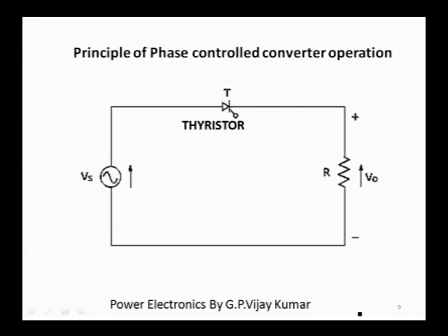You have already seen what commutation is. Commutation is the process of turning off a thyristor. So, this is a method of natural commutation, we are turning off the thyristor by natural means. It gets turned off whenever the voltage source becomes negative during the negative half cycle, so the thyristor is reverse biased. Another condition, already told in the commutation class, is that it needs sufficient time to move from the forward conducting mode to the forward blocking mode.